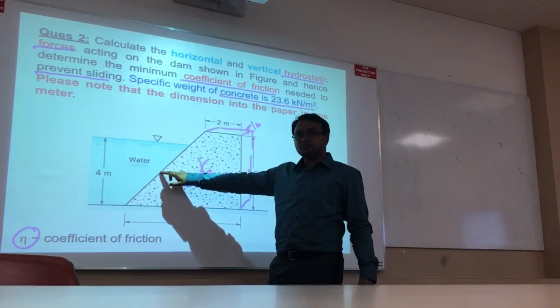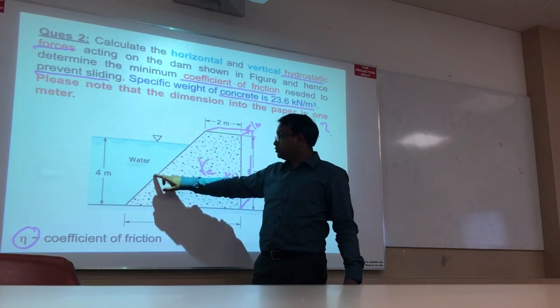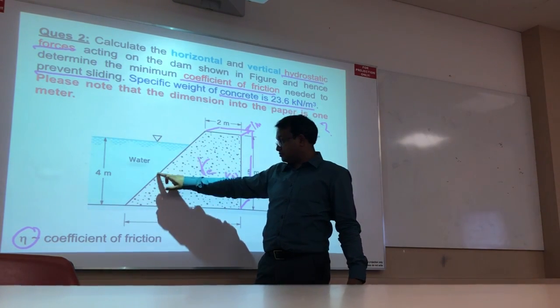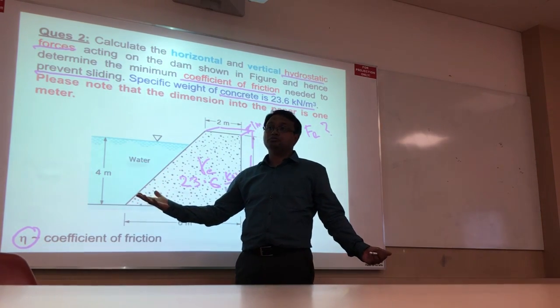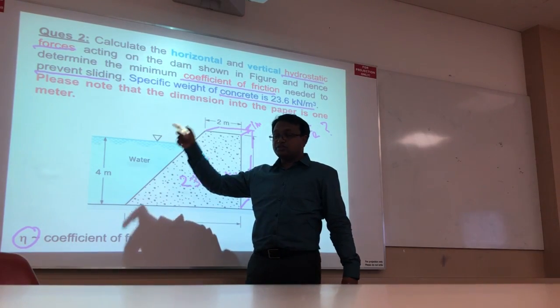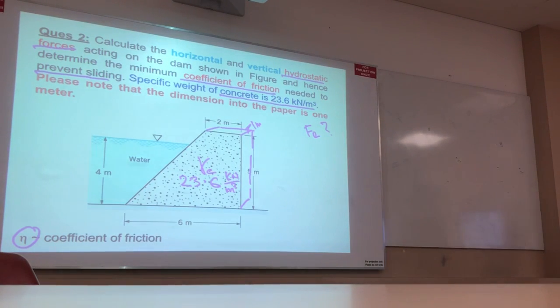Definitely here, right? I tell you the distance from the surface of the water to this point. So from here to here. What is the distance? 4 by 2, right? Distance is 4 by 2. So that means hydrostatic force F is rho g Hc times area. So I can easily calculate total hydrostatic force, no problem. Fr becomes rho g Hc area.